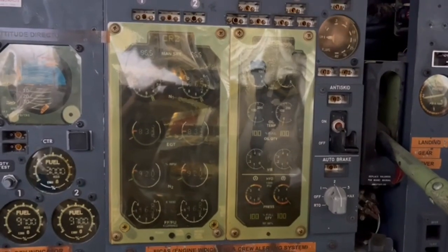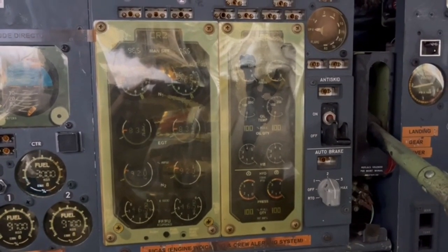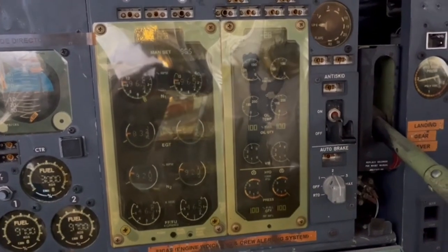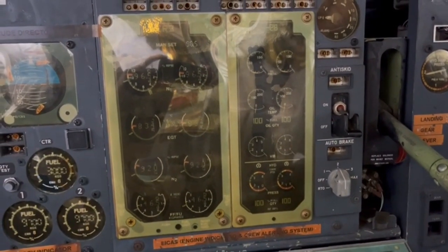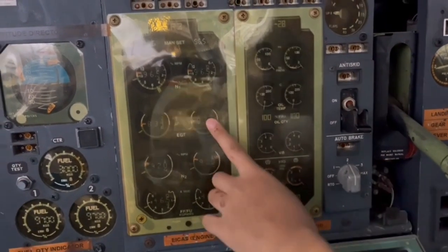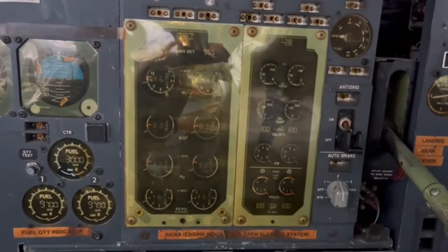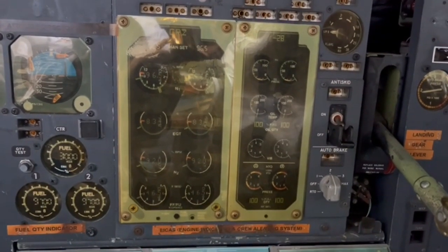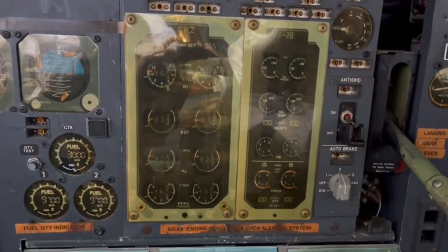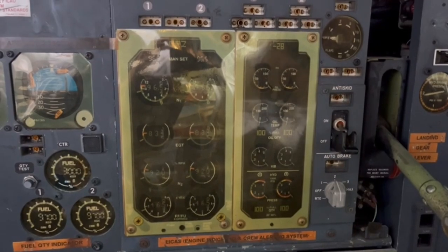So the function of ECAS is, first, engine monitoring. Pilots will use it to track performance during engine start, takeoff, climb and cruise. The second one is abnormal condition alerts. For example, let's say the crew notices an abnormal increase in EGT on engine 2 during takeoff. The red needle on the EGT gauge will cross the limit mark. Based on the ECAS data, the pilot may decide to abort the takeoff or throttle back and monitor further. The visual cue is crucial for decision making, even without text-based alerts like in modern aircraft.